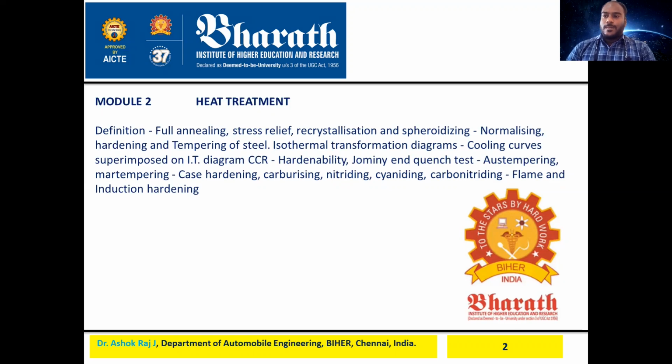When will they do it? Heat treatment is nothing but, after doing any process like casting or any other type of manufacturing process, if you want to increase the physical properties or change the microstructure. Why do they want to change the microstructure? If you change the microstructure, obviously strength, hardness, ductility and toughness will change, especially the mechanical properties. For that purpose only, heat treatment is generally done.